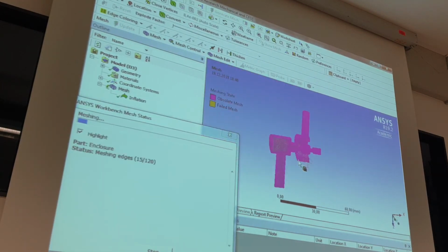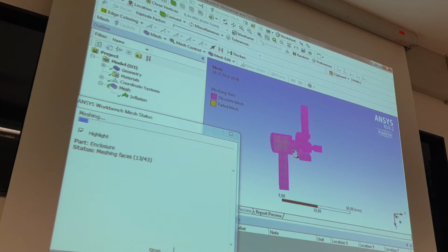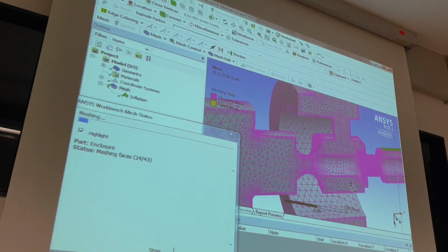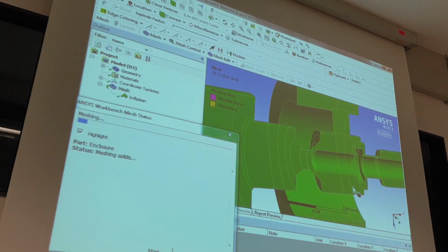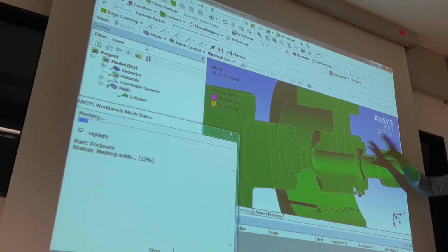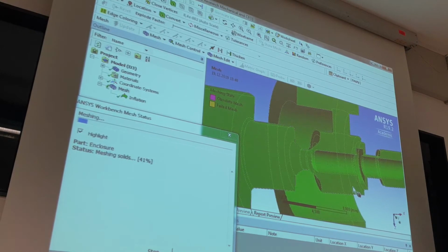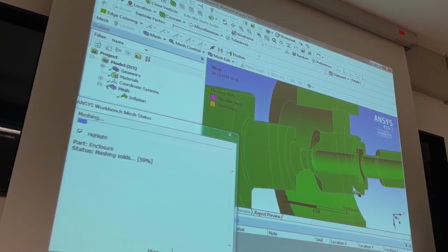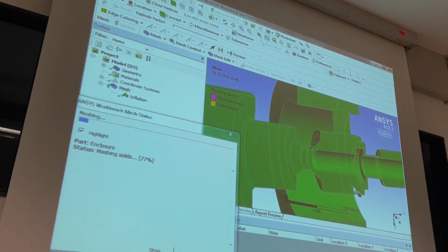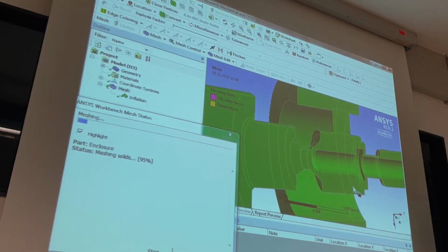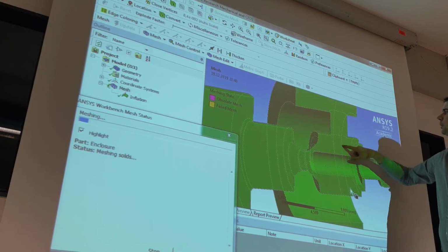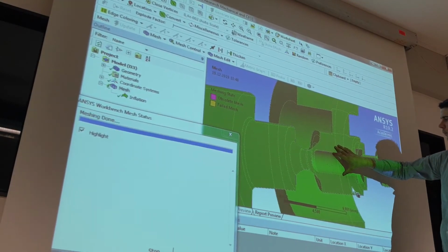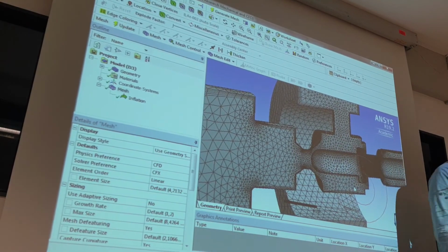Now we have this mesh, and in two weeks we will do the simulation. In your practical work and in your examination, you also get a question, for example, from an examination. You see this picture, and the question is, what do you have to do to create hexamesh? The answer is easy. You divide, for example, here. And then you have this geometry full with hexamesh.